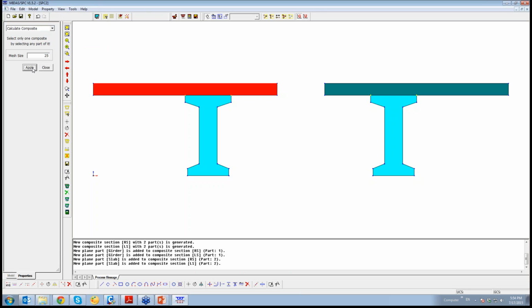Okay, so as you can notice at the bottom, the properties will now be calculated and it will be shown in the process message. Usually whenever any error pops up, it will also be shown. It is saying that if these are apart, then the properties would be calculated incorrectly. So you'll have to check that the drawings are accurate and the properties are calculated.